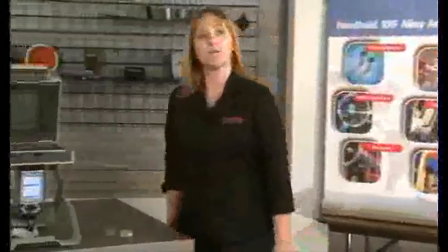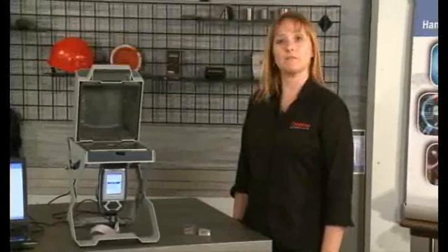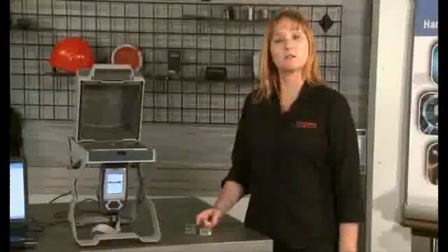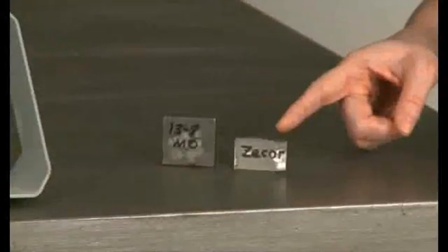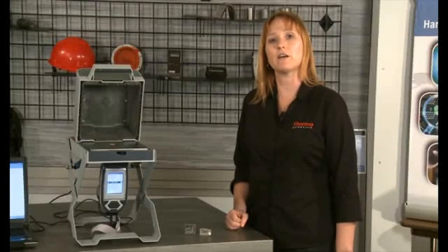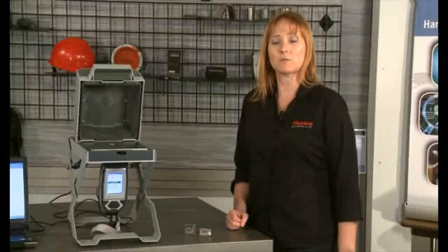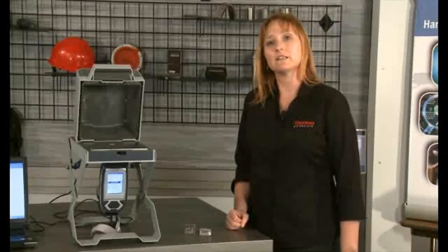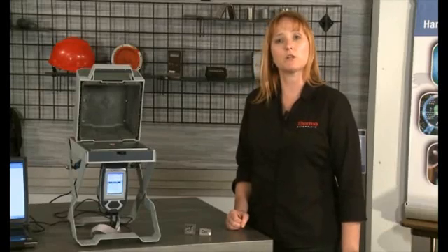However, this huge benefit has one minor drawback. A small percentage of alloys may contain significant amounts of non-detectable elements. 138MO, for example, contains 1.5% aluminum, and Z-core contains about 6% silicon. In these cases, the instrument will normalize to 100%. So, if we have a stainless steel alloy with the alloying content comprised of non-detectable elements, such as 6% silicon, the reading for all elements except silicon will be normalized to 100%, therefore causing a 6% high bias distributed proportionately